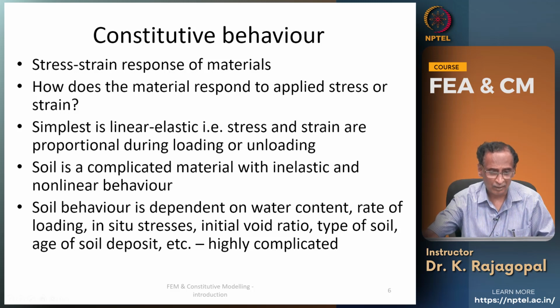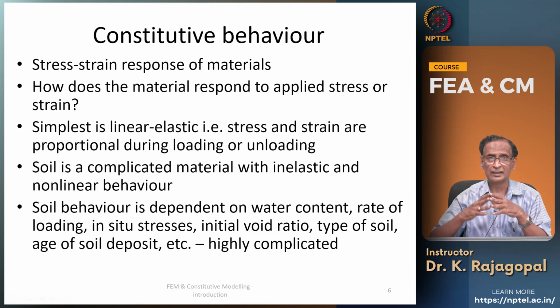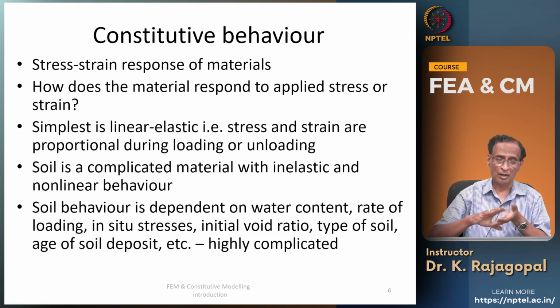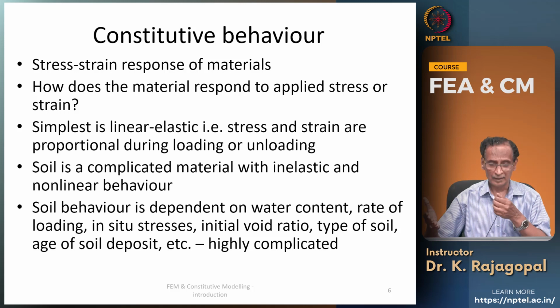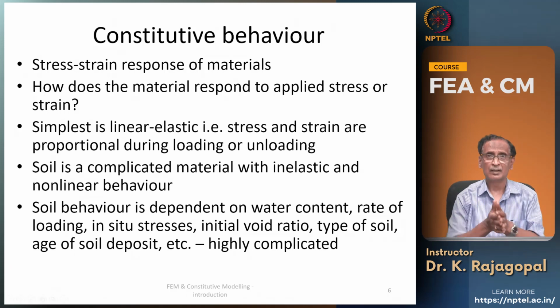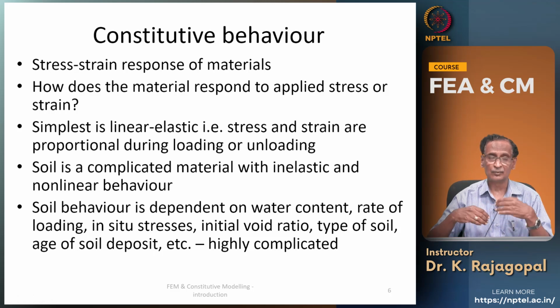And then the age of the soil deposit, especially in the case of clays, might increase the bond strength, and because of that the strength may be more, and so it is highly complicated. But through the finite element analysis we should be able to replicate all these behaviors.